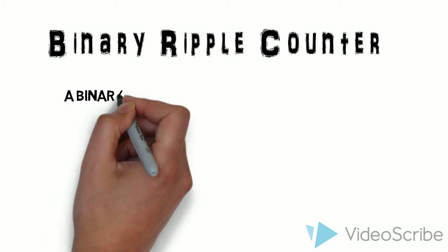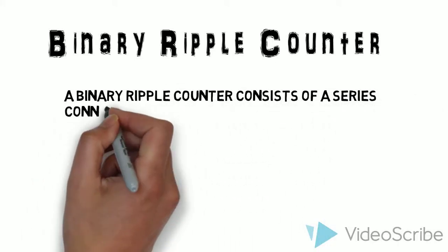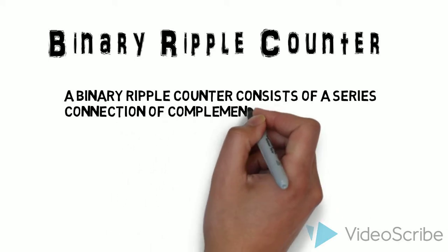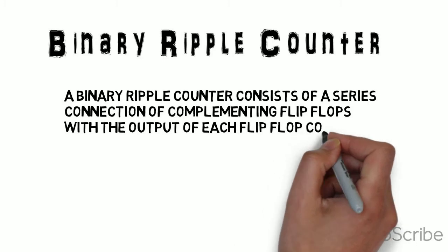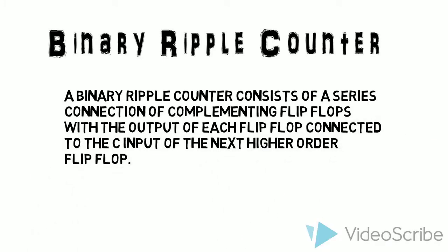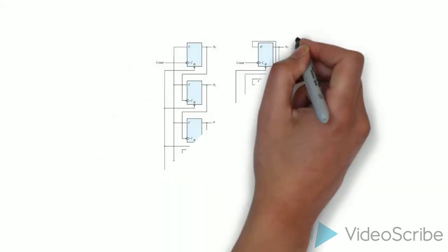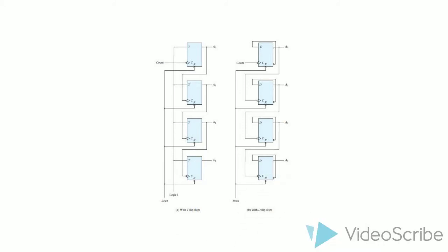A binary ripple counter consists of a series connection of complementing flip-flops, with the output of each flip-flop connected to the C input of the next higher order flip-flop. The flip-flop holding the least significant bit receives the incoming count pulses. A binary counter with a reverse count is called a binary countdown counter. In a countdown counter, the binary count is decremented by 1 with every input count pulse.